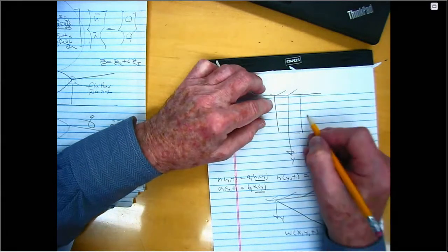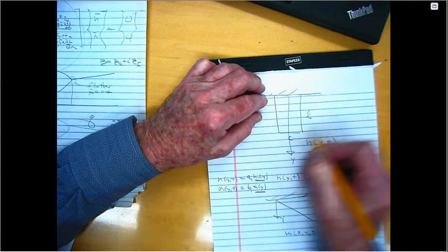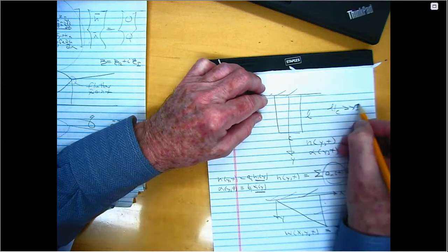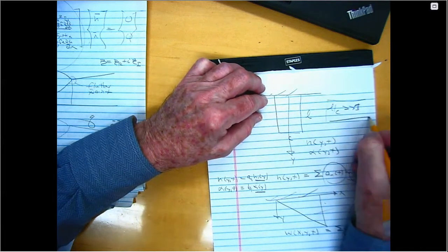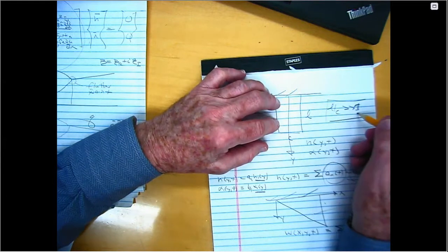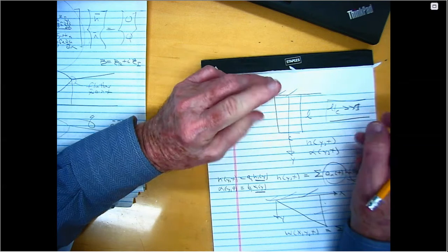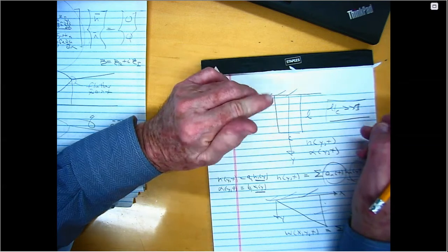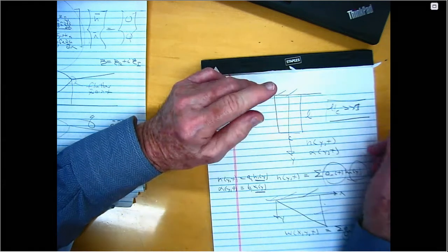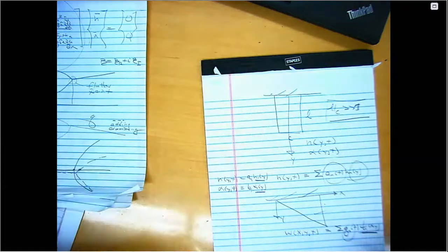So if this L gets much larger, if L over C gets very large, it turns out that it's usually the first torsion mode. But as L over C becomes higher and higher, it's a higher and higher bending mode. So it's first torsion and third bending that's critical. And then if I go to a higher aspect ratio, then it's fifth bending and first torsion. And that's been observed both in experiments.